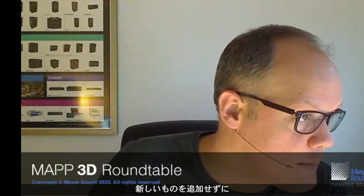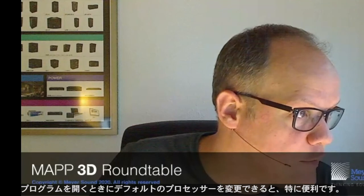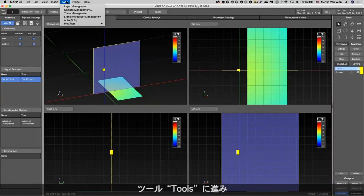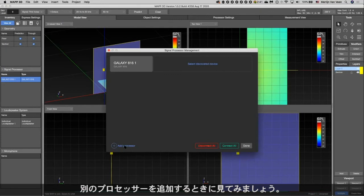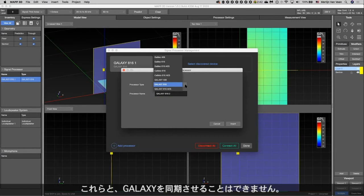Can we change the type of signal processor without adding a new one? This would be especially helpful if we could change the default processor when we open the program. We go to tools, and then from tools we go to signal processor management, which brings up the following dialog. And let's see, when we add another processor, whether we get to choose Callistos and Galileos as well. Ooh la la. They're there.